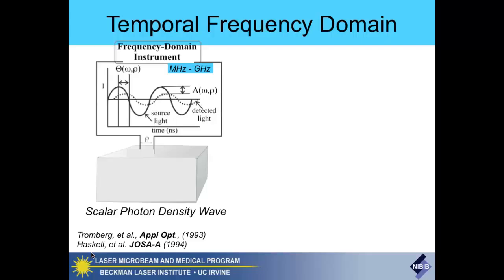We use laser diodes, but what's important is: how many of you have heard of a bias T? It's a little mixing circuit that allows you to mix AC and DC together. So why is that important with a laser diode? Laser diodes all have threshold current levels that you need to hit.